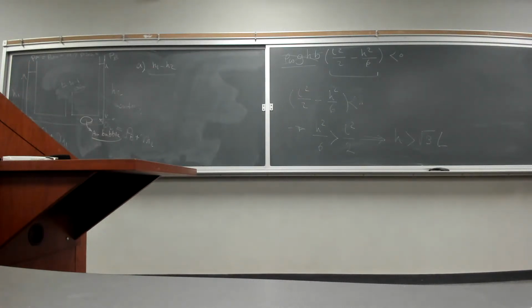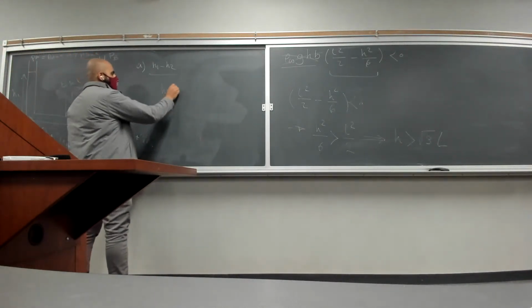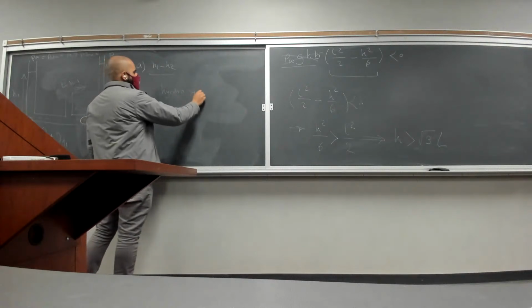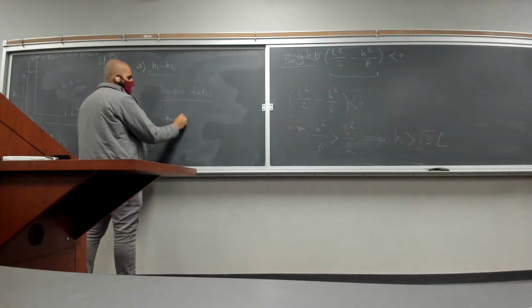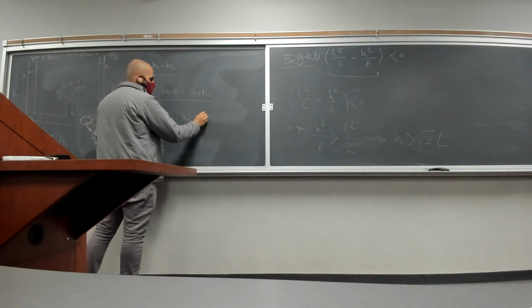Well, what is the relationship between these two pressures? We have an air bubble stuck here. How is it going to change our problem, essentially, our pressures? To answer this question, you have to go back to the nature of hydrostatic pressures. The idea was it mainly depends on height or depth.